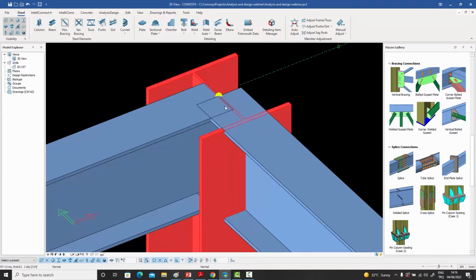But then when we entered the beams, the beams did not create extra nodes over there. So there are not three nodes over there. Only when the first column was entered was a node created. When the beam was entered, the program noticed that the node already exists at that point.